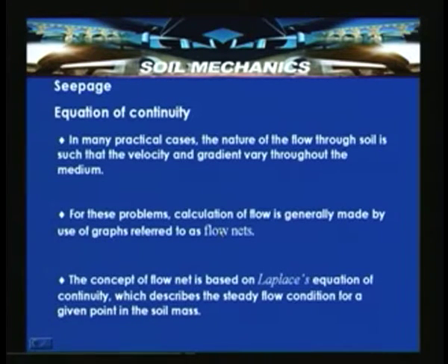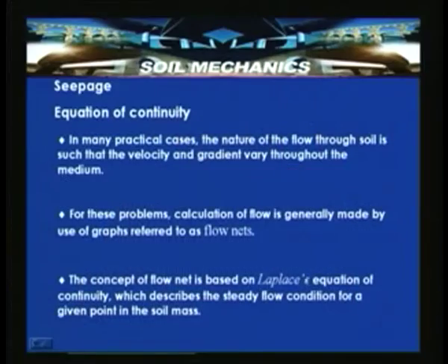flow net methods. This flow net method is nothing but the solution of the equation of continuity, which we are going to derive very shortly. The concept of flow net is based on the Laplace equation of continuity, which describes the steady flow condition for a given point in a soil mass, occurring in a saturated soil medium.